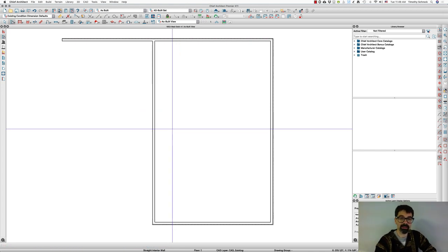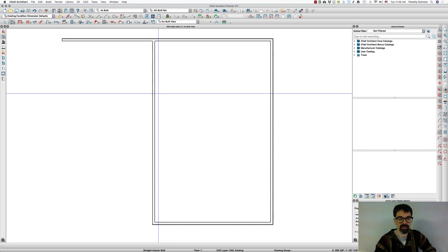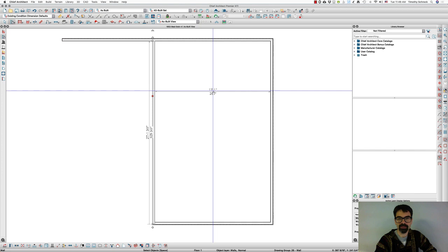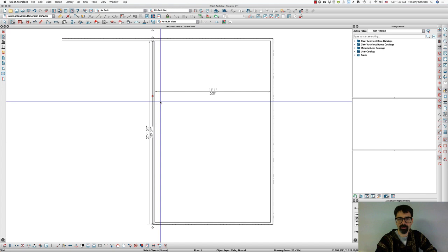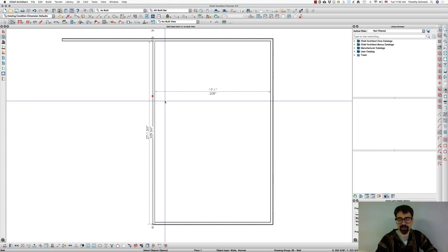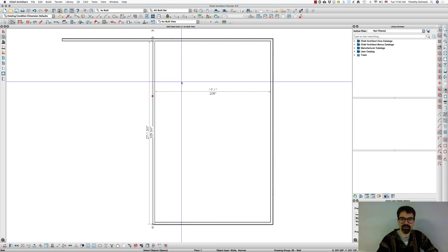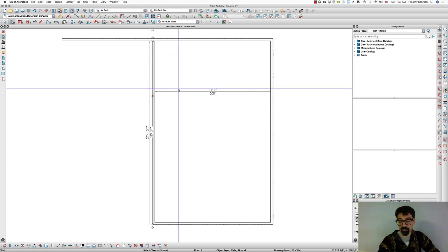Also, my as-built dimension set is shown as drywall to drywall because typically you're measuring an existing finished space. Sometimes I go into a project that has been renovated or started renovation, and so drywall has come off and I'm measuring stud to stud. You'll want to be aware of that and change that location when you open up, if you're using my template or your template, so it is measuring stud to stud.